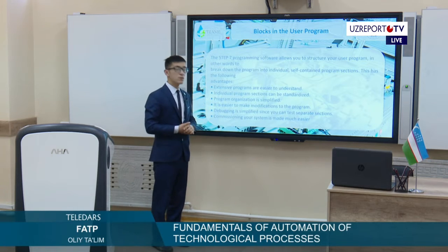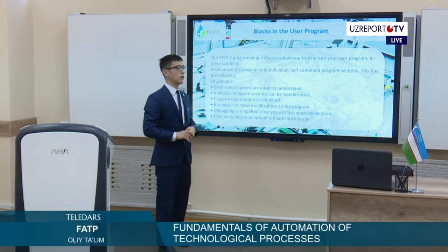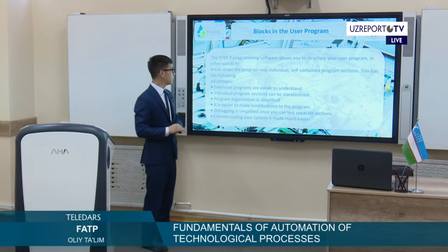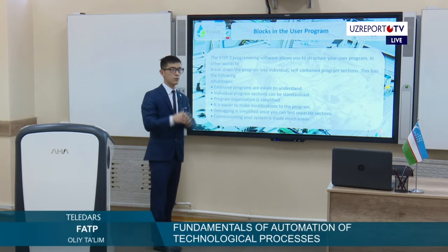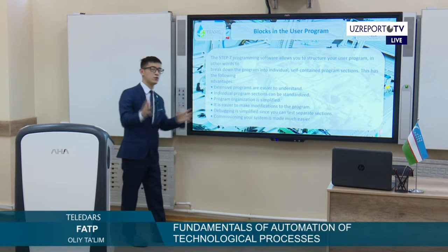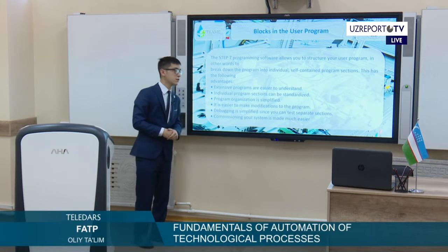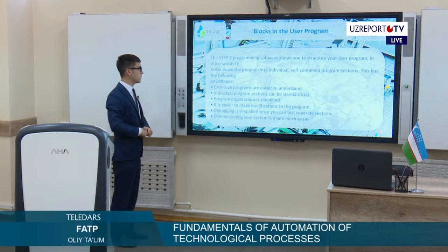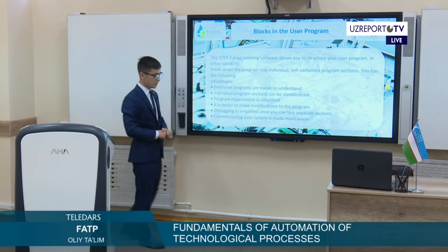Today we will use the block program in the language of LD, ladder diagram, and let's talk about the advantages of this program, why we choose Step 7 and why we choose ladder diagram as the programming language of the controller. First of all, extensive programs are easier to understand.